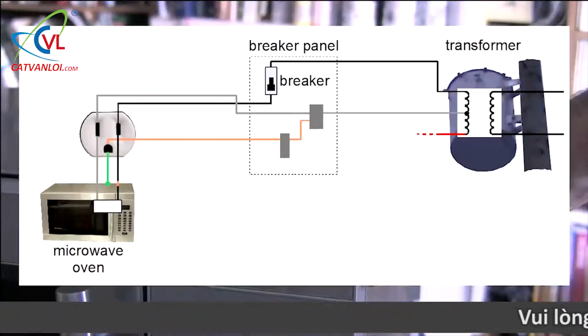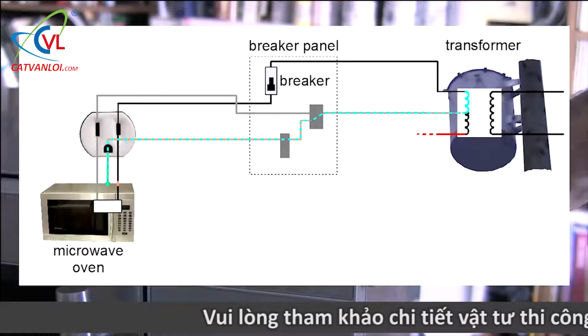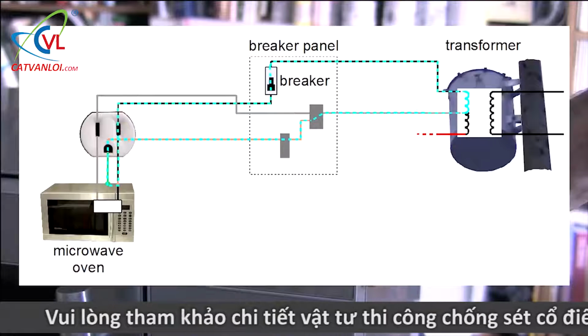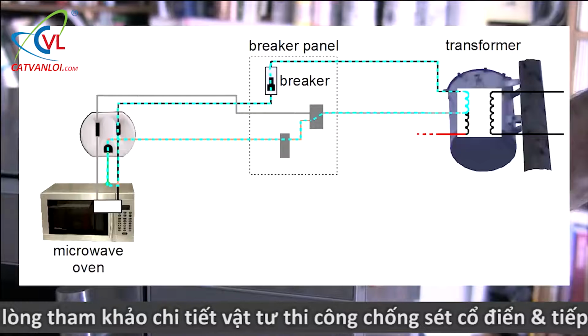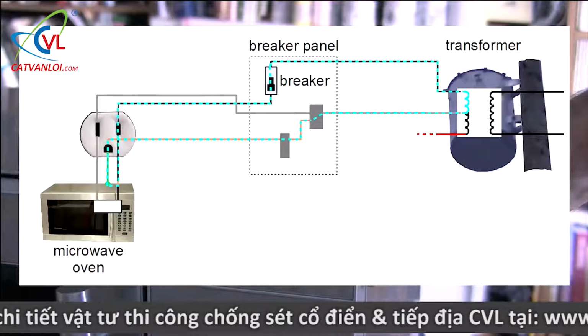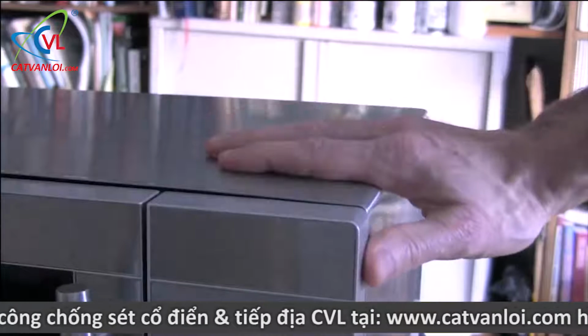The problem starts when insulation on the hot wire breaks, and the wire touches the microwave oven's case. Since the case is connected to the ground wire, we now have this complete circuit, along the ground wire to the breaker panel, then along the neutral wire, onward to the transformer on the pole, through the transformer's coil, back through the hot, through the breaker, and continuing to the hot in the microwave oven, where it's touching the case. There's very little resistance along that circuit, and so the electrical current will be high enough to trip the breaker, which opens the circuit, making it safe to touch the microwave oven's case again.